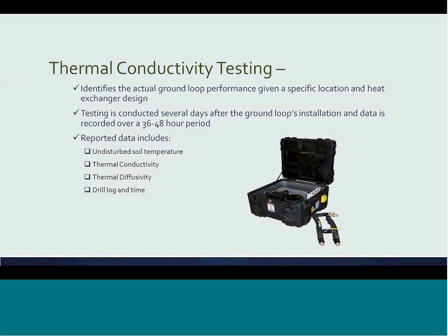what we are counting on here is a deep earth temperature, and there's a lot of impact to horizontal systems that you'll see in a slide further down this presentation that may cause this test to not be interpreted correctly. So the conductivity test is really the best way to determine drilling conditions for project budgeting, the deep earth temperature, and the soil conductivity. And from this information, a thermal diffusivity may be calculated.